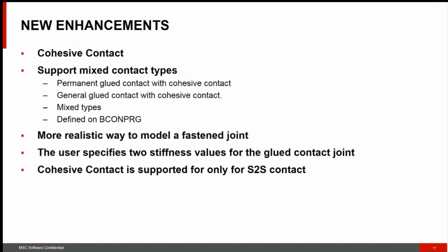The last option that I'm going to talk about is the cohesive contact capability that has been added to Nastran 2017. They call it cohesive contact, or the flexible contact. In modern industries, product structures like airplanes and automobiles are becoming more and more complicated, with many parts and assemblies. The process may be done through a variety of means, for example contact or CGAP or other elements, but contact is the easiest way to assemble these parts, right? That's why we use the glue contact.